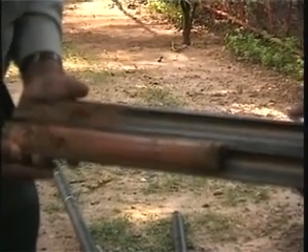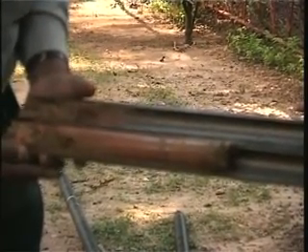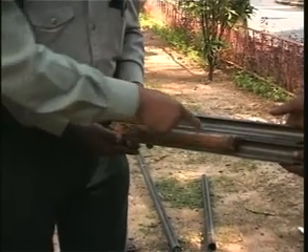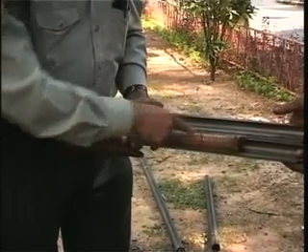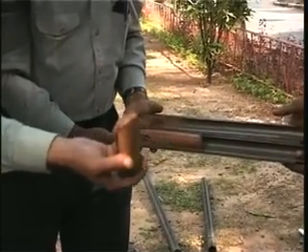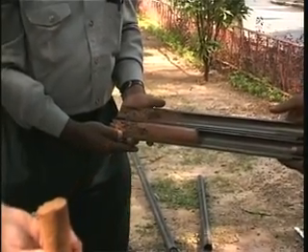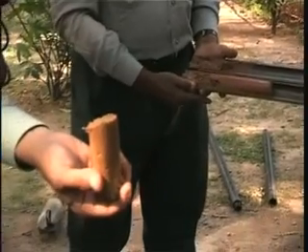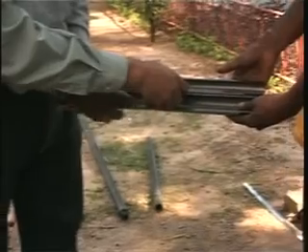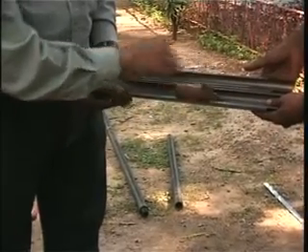So if you recall, this is the bottom end of the sample, and that is the top end of the sample, and you can see that the sample was moist near the top, and it was becoming dry as we went downward. So this has got a lot of sand and silt and other fine grained soils. It has got some cohesion as well, and that's how we identify the sample.